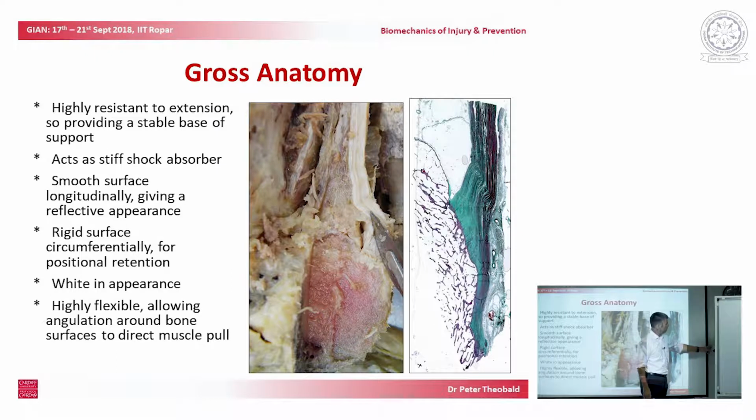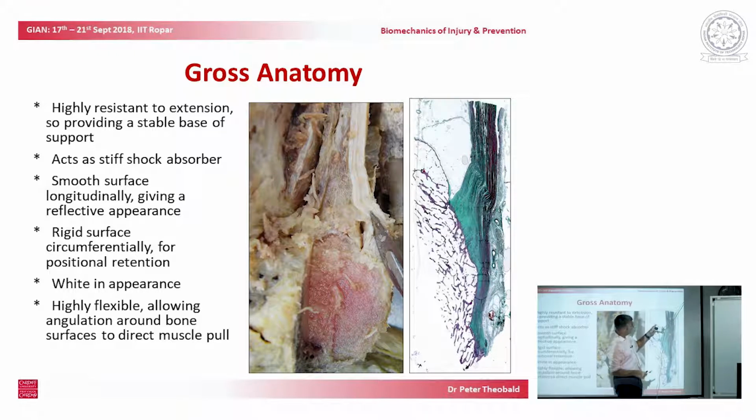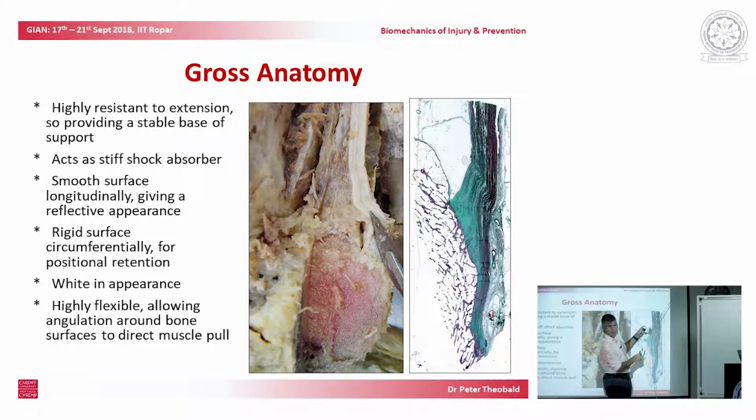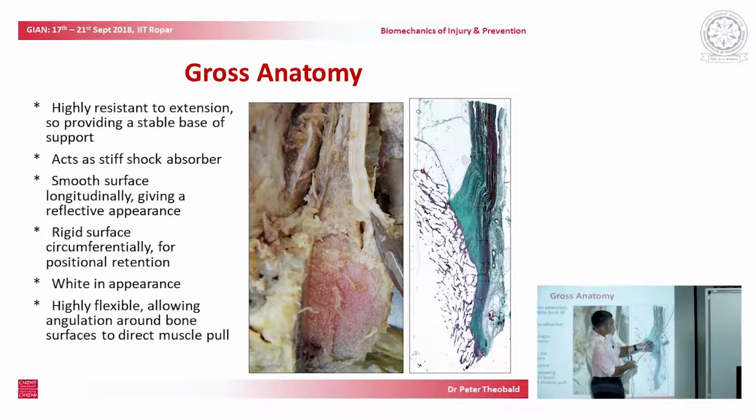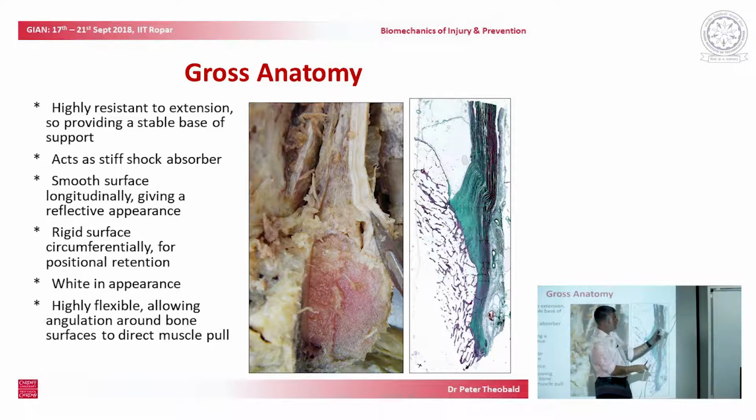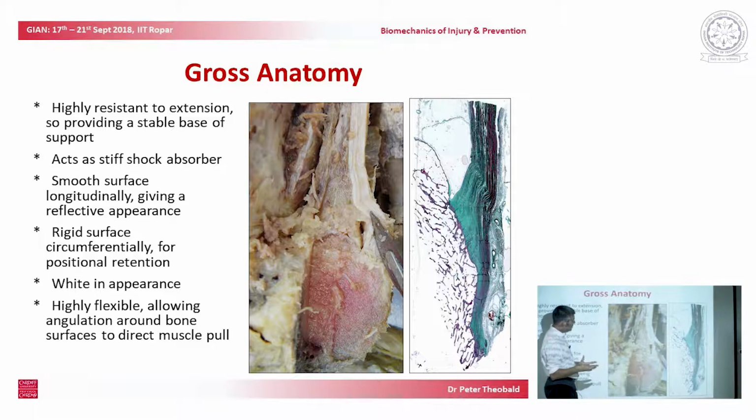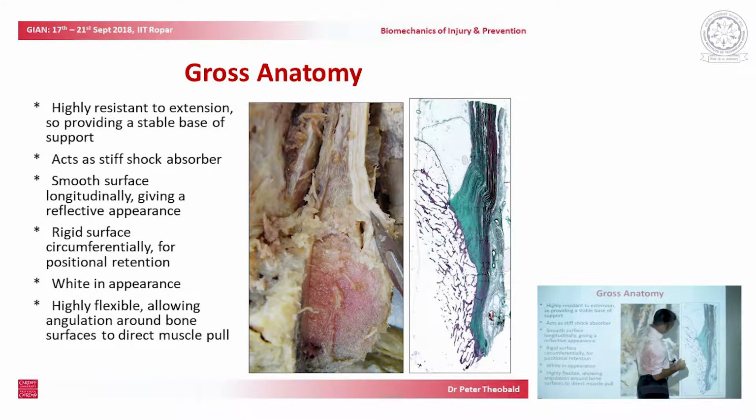And a good example is here, actually, whereby we have a similar situation. We have our rigid box and our flexible cable. And the engineers have designed this rubber grommet so that when we load it, we see that there's only a gentle curve at that interface. And so the risk of a stress concentration happening at the interface between the two is mitigated. And so the risk of premature failure of the tendon is mitigated against as well. The human body does that in a very sophisticated way.